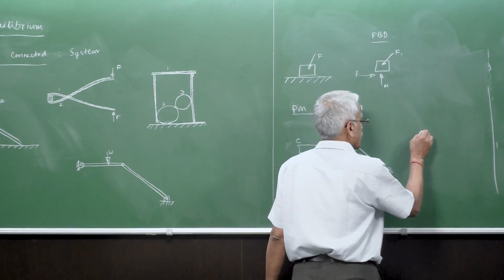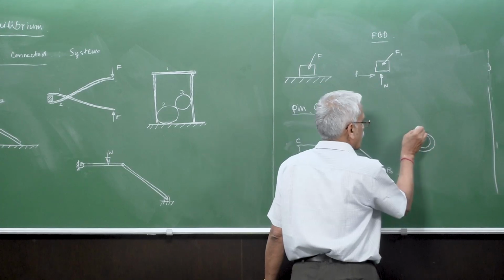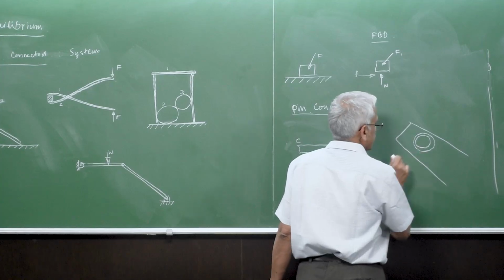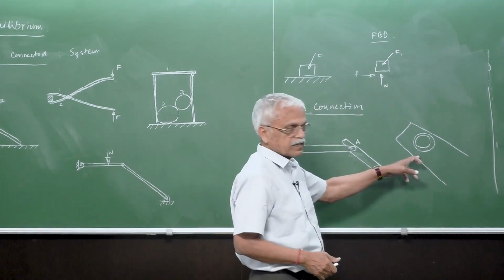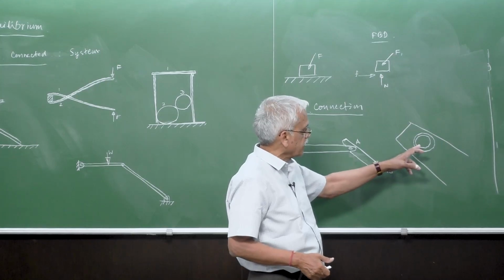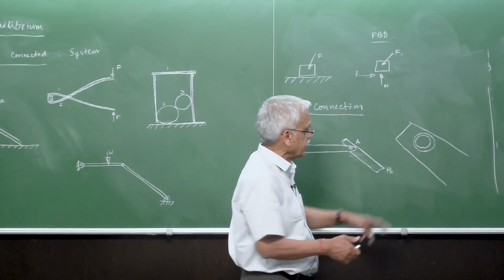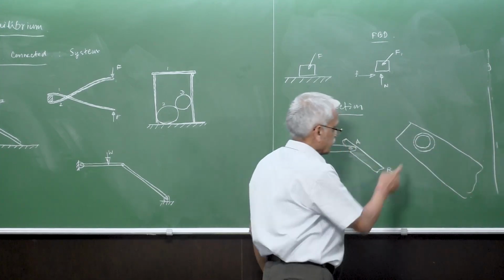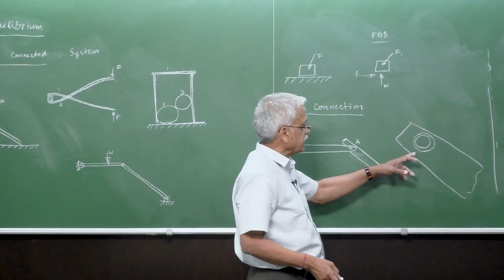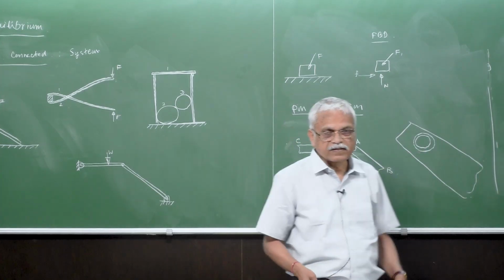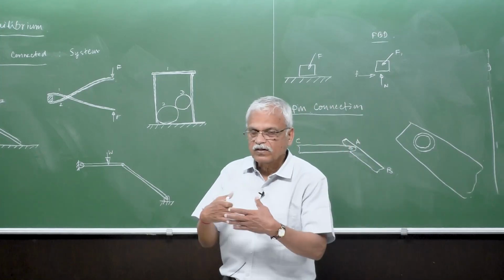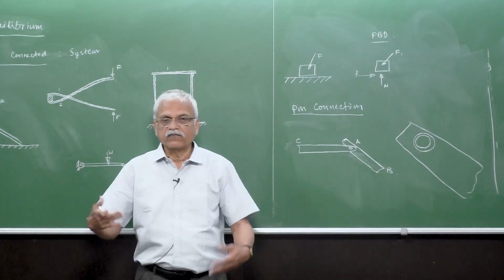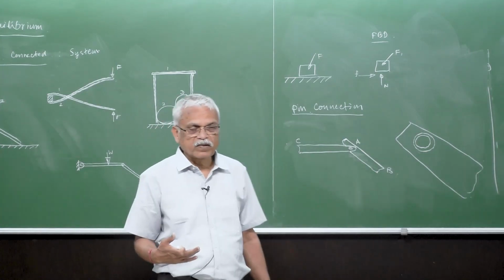So the pin is sitting in a hollow hole like this, right? So what kind of forces can you apply onto the pin by the rod here? So this is the rod. So this is all blown up. So if you understand the forces that can act here, if there are two surfaces in contact, we know if there is no friction, then the only force that can exist is the normal force.